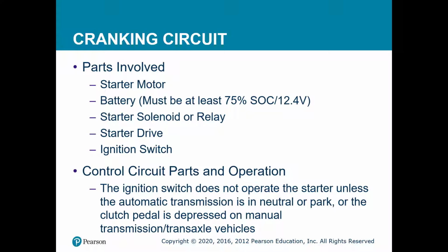The next thing on our list would be our starter solenoid. When I say solenoid and relay, I have both of them up here. Many systems contain both, and we've covered what a relay and a solenoid are. Relays can carry up to 30 amps, and solenoids can carry hundreds of amps. The relay may be in series, or the relay may control the actual solenoid itself.